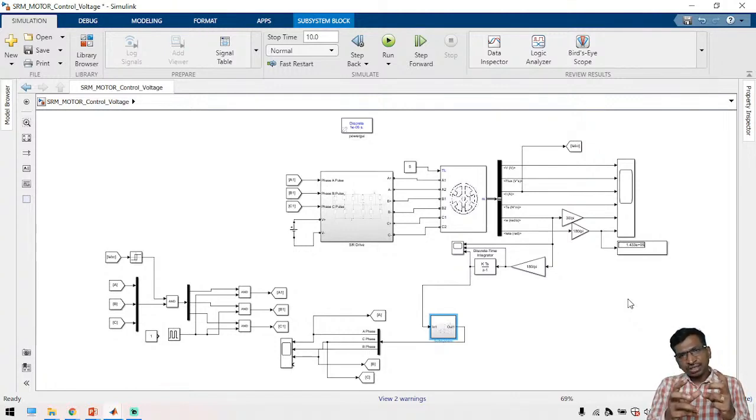That residual energy will create spikes in the rotor current. Due to the rotor current, the torque will get huge disturbances. Due to the magnetic behavior of the inductance, the torque has so much disturbance. And we can also run this motor at a high speed, so that high speed will also create disturbances.